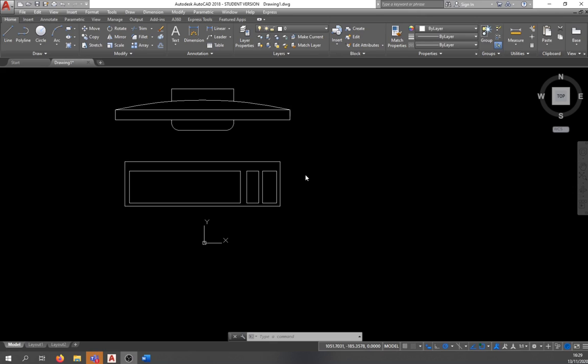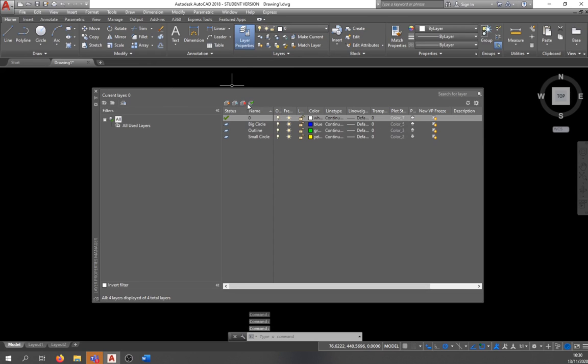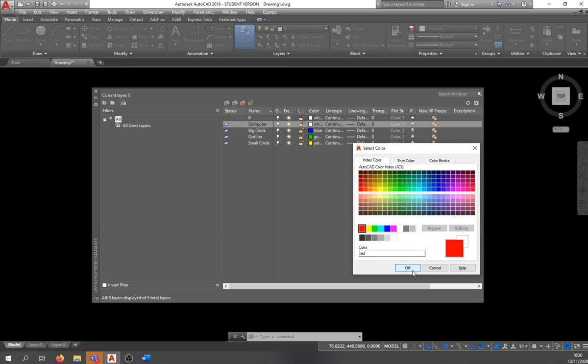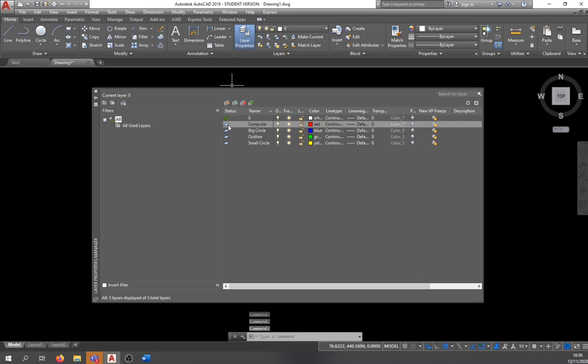And remember, we drew this block on a 0 layer, but usually in a drawing we'd insert it on its own layer, so there will be its own layer for computers. So I'm using the same drawing file from the clock we did last video, so I'll open up the layer properties, make a new layer, and call it computer. I'll make it stand out a bit, I'll make it red. So there we go, and I'll bring that up, make it active, and close it down.